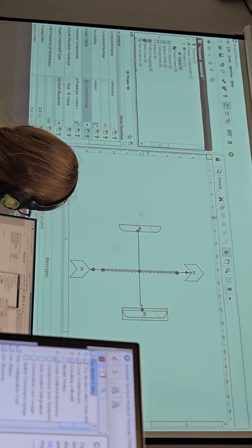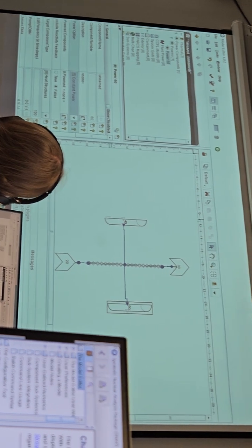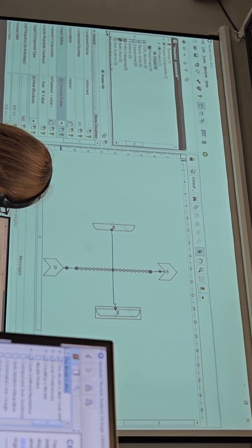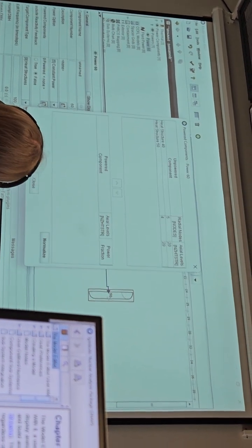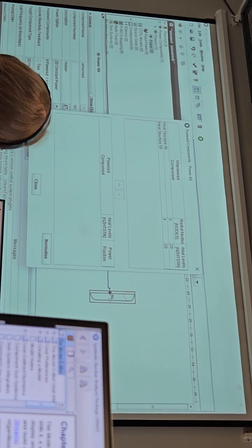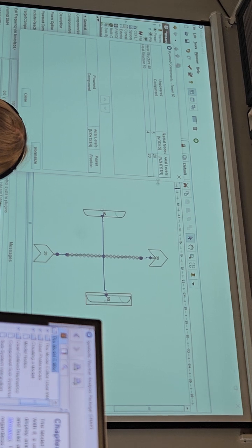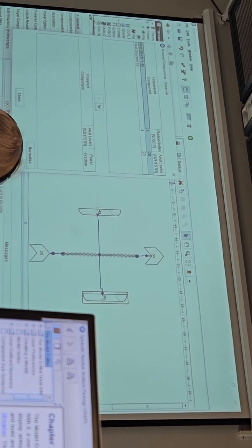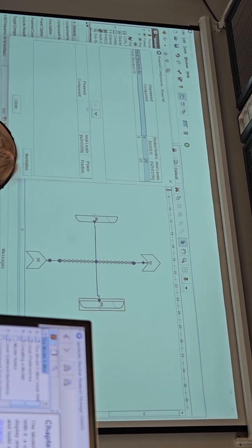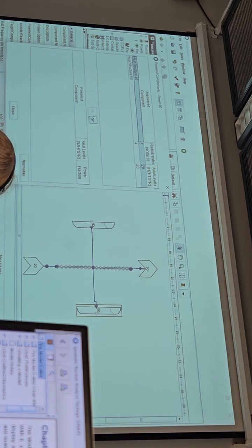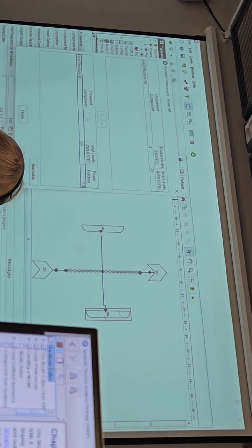We need to power the internal heat structure here, structure number 40. We just click here, and we have a choice between two heat structures, number 40 and number 50. So 50 is a glass tube, so in our case it is number 40. Just select heat structure number 40 and press the back direction arrow.